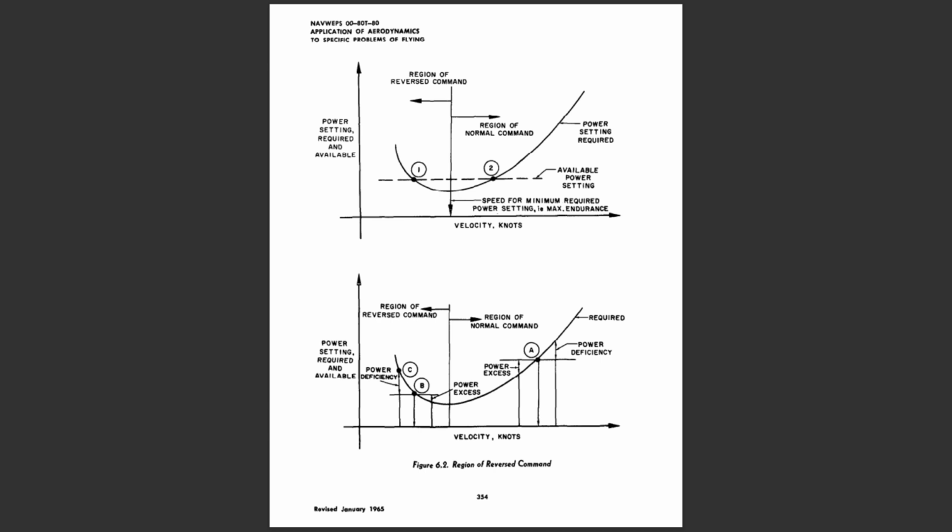If the airplane characteristics are low wing loading, high L/D, and high lift curve slope, the increase in angle of attack at point B will produce a transient motion in which curvature of the flight path demonstrates a definite flare. That is, the increase in angle of attack creates a momentary rate of climb, or reduction of rate of descent, which would be accompanied by a gradual loss of airspeed. Of course, the speed eventually decreases to point C, and the steady-state rate of descent is achieved.